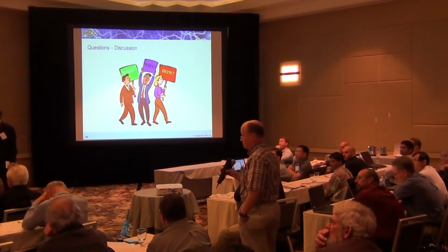The answer is yes. We often speak of, especially with GOOSE, having virtual wiring where one GOOSE message can replace literally hundreds of copper wires in a substation. Additionally, with process bus, where today there are literally tons of copper in the ground from the circuit breaker into the control house, this is all being replaced right now by a couple of fiber cables, bringing all the measurement information from the yard into the control house.